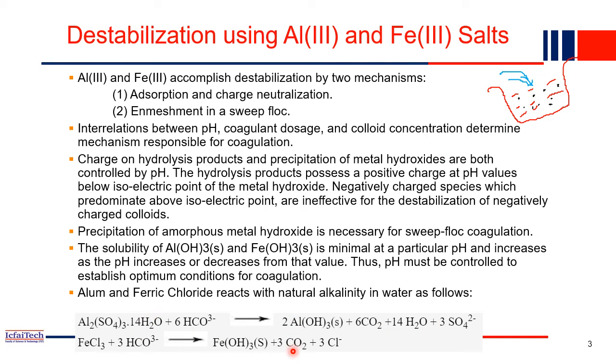Based on this equation, the entire thing happens, and when the ions charge the particles, positively or negatively, what will happen? These will combine together and make the flock. The flock is nothing but when it combines, it aggregates all the suspended particles, and the dimension increases, that we call flock. Once flocks are formed, they will simply be deposited at the bottom.